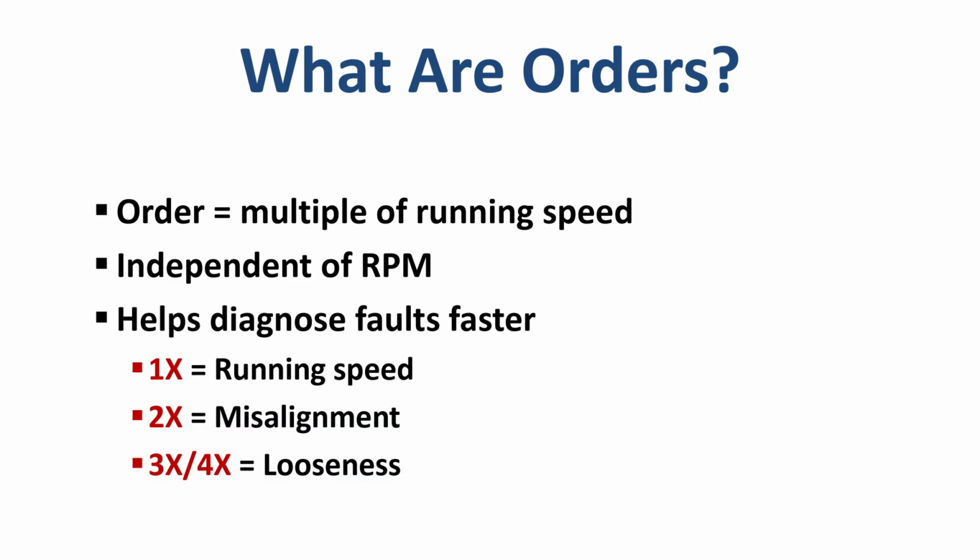so that it will be very easy for us to differentiate between the peaks, whether the peak is synchronous or non-synchronous or sub-synchronous, right? So it helps us to identify whether the fault is related to misalignment or unbalance, or it can be something related to looseness, or any kind of complex vibration patterns.